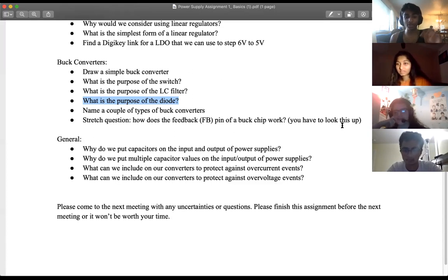And when you open your switch, all of a sudden no current is coming in. So your inductor's like, whoa, I want current to keep flowing. So it's going to convert that magnetic field. That magnetic field now has a path to convert itself into electrical energy, where it takes the form of current and flows through your circuit. The diode is, like Shri said, our low resistance path for dissipating that excess energy because we don't want it in our system.